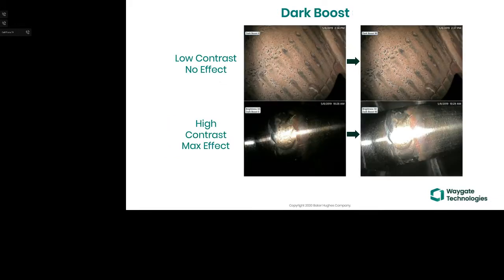It's a lot of words to say, okay, what does that really mean when I'm looking at an image? You look at the left-hand side, and you can see that it looks a lot like changing the brightness. I have another picture I'm going to show you earlier, but brightness on the lower left image would cause that weld to glare out. On the right-hand side, you see the weld is somewhat a little more glare, but you see the weld back in behind it down at about 5 o'clock on the image. So data that's back in dark areas becomes much easier to see.